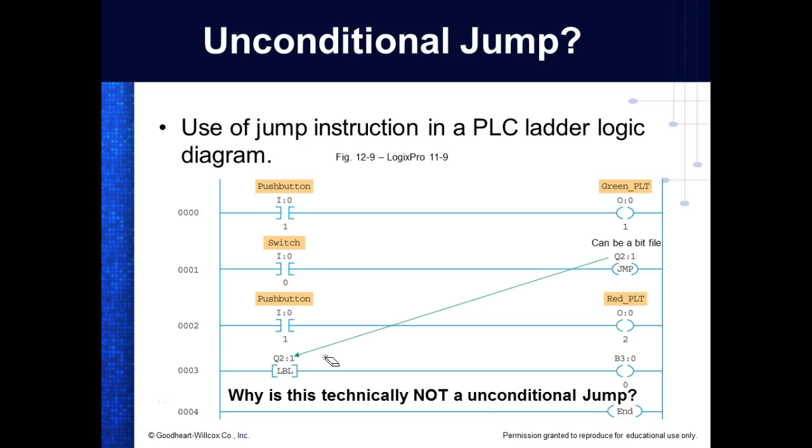It could be a reed switch, a Hall effect, an inductive sensor, an optical sensor, any type of sensor that's sensing different things. So if it's a certain height, I could have a through-beam sensor, which we talked about in PLC 1. If it trips that, then it would do this. If it doesn't trip it, then it would do that. And that's the power of the jump instruction. So using these jump instructions, we can deliberately make it skip over a section of a program until what we're looking for is true.